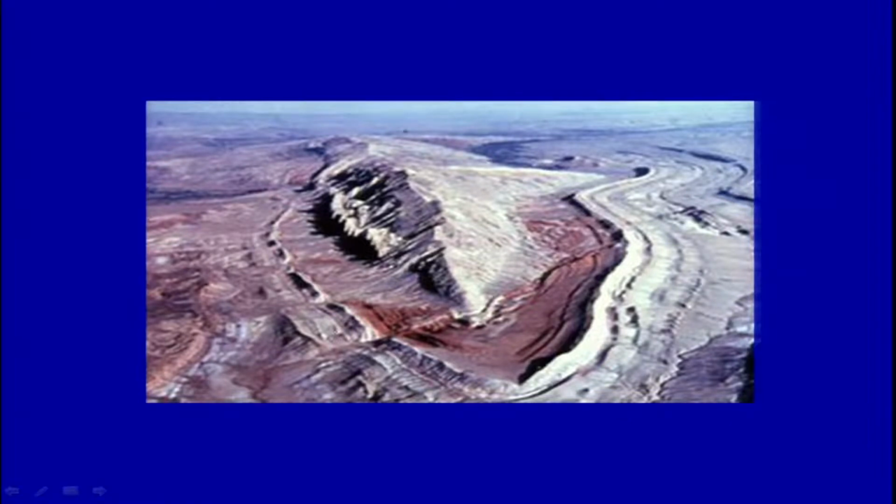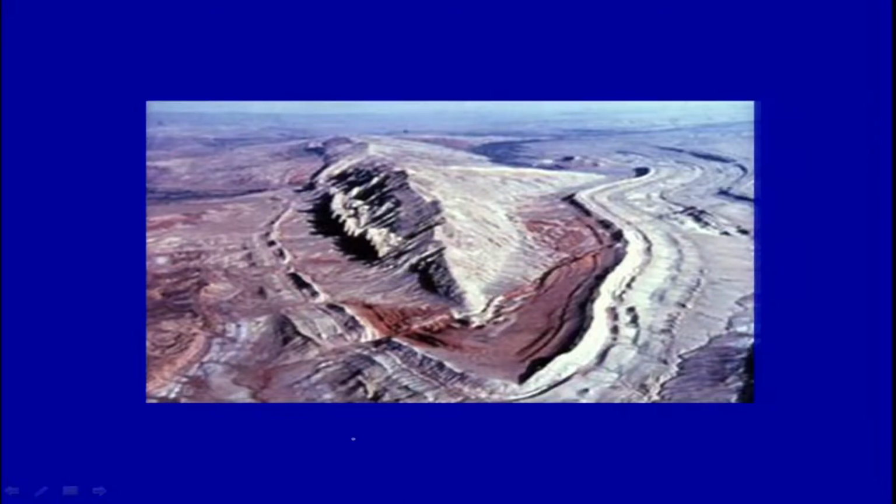As we were talking about, if you are having an anticline, for example, if you put an anticline here, and then if we ask you to put the strike and dip, so on the plan view what you will put is that this will be your fold axis, and the beds are dipping, this is a strike and the beds are dipping in this direction here, and this is the strike here and beds are dipping in this direction. Okay. So you have the clear cut fold. This indicates that the terrain is folded.